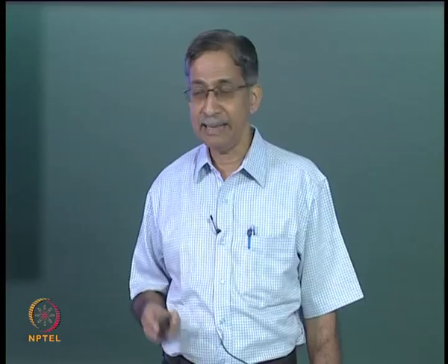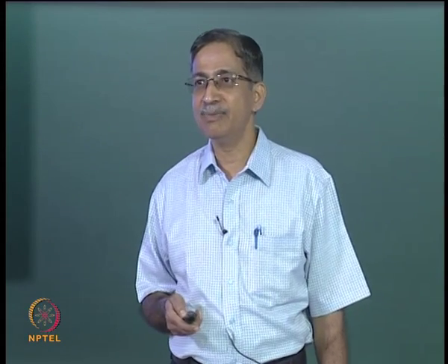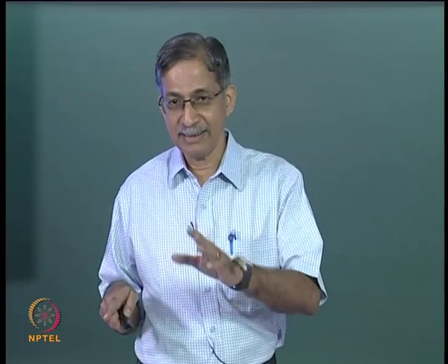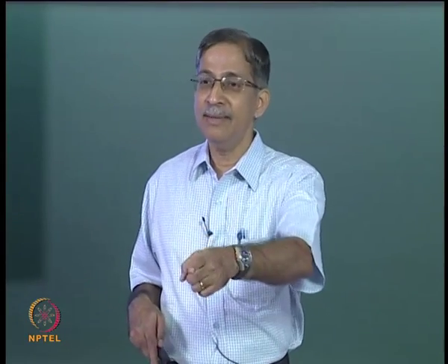Okay, so you also have support settlements here at the redundant coordinates. That is, you have D4 and D5 as minus 0.005 and minus 0.020. I would like you to think of what you need to do. I am not going to solve it here, but that is something for you to worry about. Supposing I had a rotational slip theta A equal to 0.001 radian, how would you deal with it? So please note down, that is a question you will get in your examination.